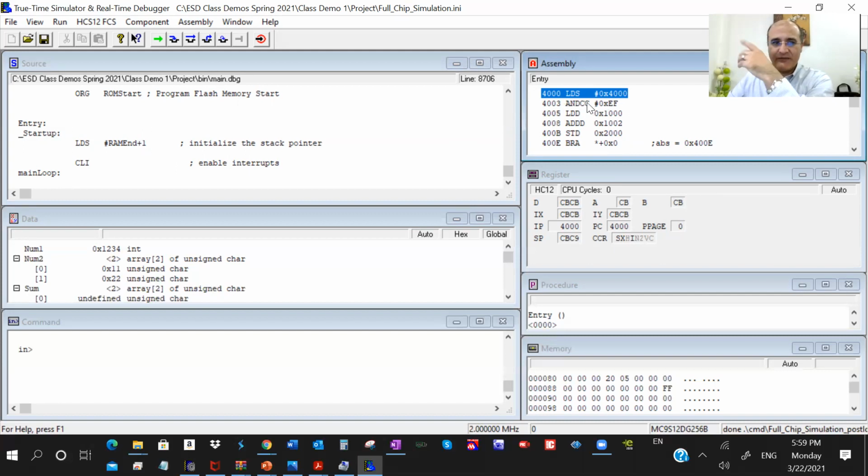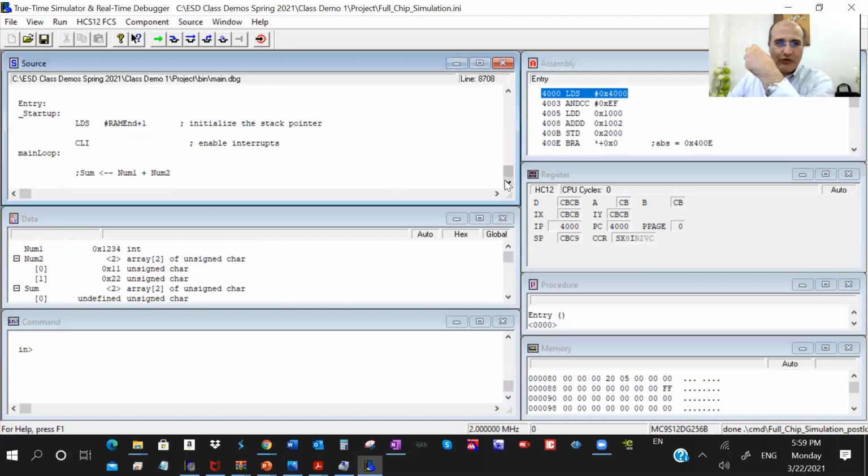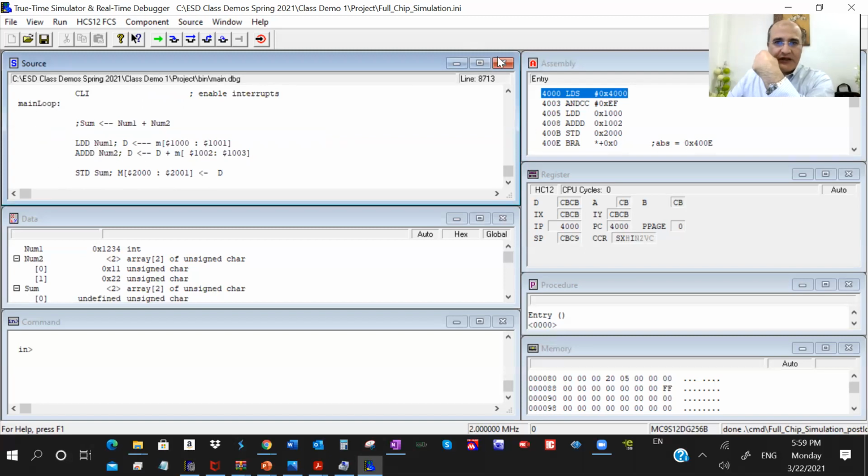This is the assembly instruction. So in this step, the assembly code we wrote is converted, still assembly code, but this column shows us the real program memory address where this instruction is going to be stored, its size, and it removes all labels. So you're not going to see num1 here. We said load num1, right? You see my mouse?